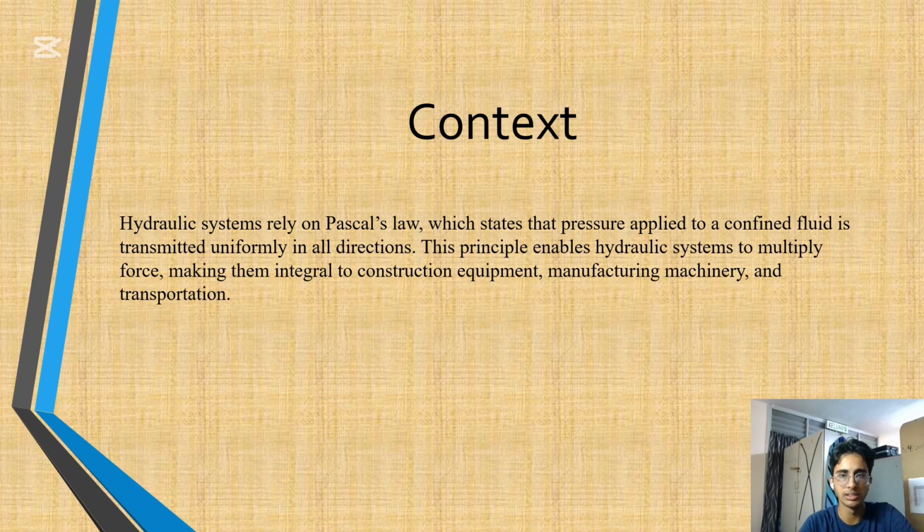The hydraulics principle is definitely Pascal's principle, Pascal's law, which is very important for this project. Pascal's law states that a force is always uniformly transmitted in an enclosed fluid, so in all directions. This principle enables hydraulic systems to multiply force and makes it easier for a small input force to become a very large output force.